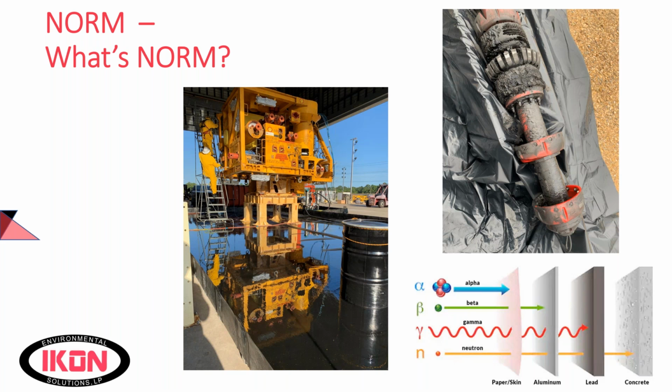As you start separating out your components, your light hydrocarbons, your heavy hydrocarbons, propane, ethane, propylene, and ethylene are the 4 main gases that are associated with the lead-210. Because radon gas is going to fall with those, and then due to the boiling points, it primarily flows with the C3 chains. So your propane line is going to have a lot of the radon gas with that.